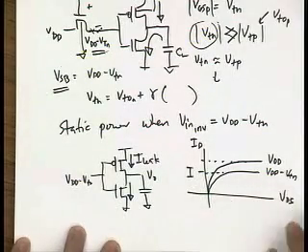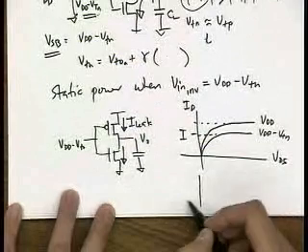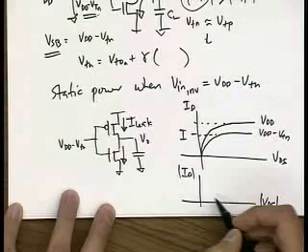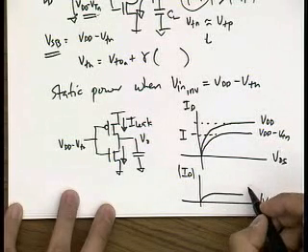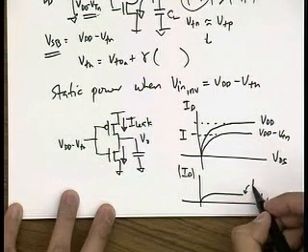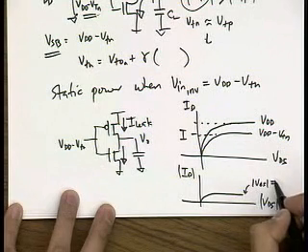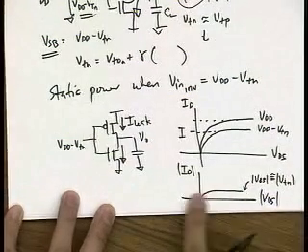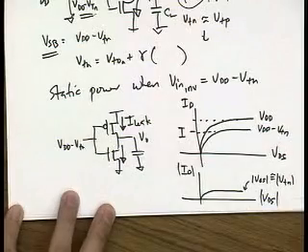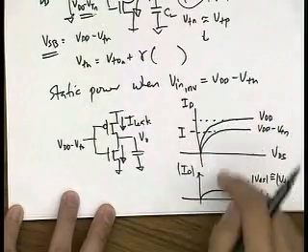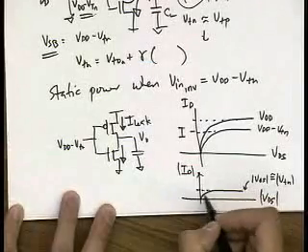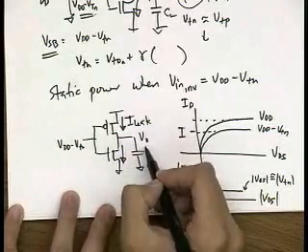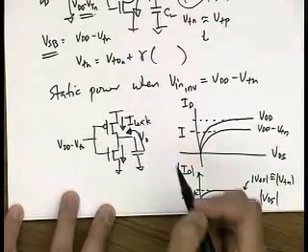Okay, so if we look at my curve for my PMOS, let's say ID of the PMOS versus VDS. Okay, it's somewhere here. I have a VGS of around VTN. Okay, so this is for the PMOS. So everything is absolute value. So it looks the same. Okay, so I do have some sort of leaking into here. So what's the current left to be able to discharge this cap?